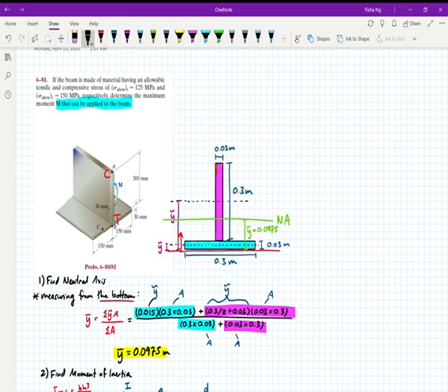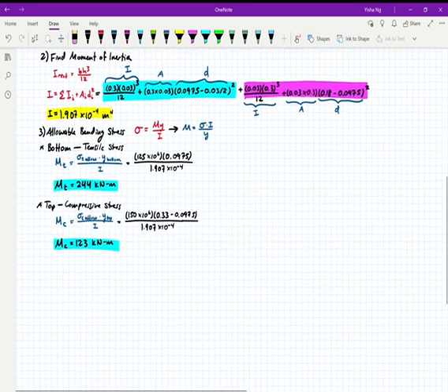If I was looking at this beam from the side and I had my moment acting like this, it would deform and turn into this. What that means, if I've got my moment acting here, is that this is in tension and this is in compression. So on this cross section, up here I've got compression and down here I've got tension. That's important because it tells me what numbers I plug in where. So we're going to start at the bottom.